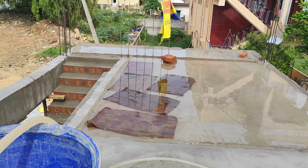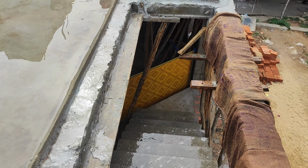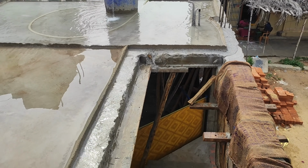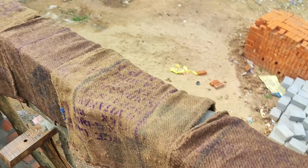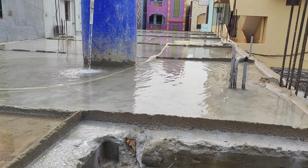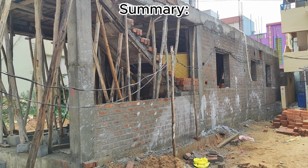This process is repeated daily, and continuous watering must be maintained throughout the curing period, often up to 21 days or until the painting stage, depending on weather conditions and concrete thickness. Curing might look simple, but it is one of the most crucial steps in house construction for long-term strength and stability.